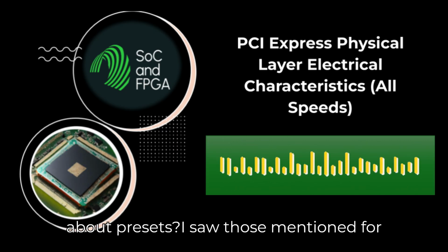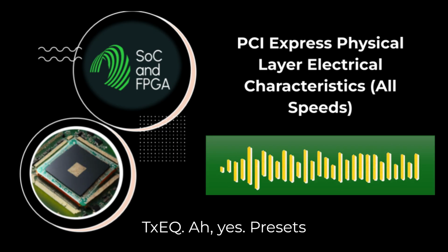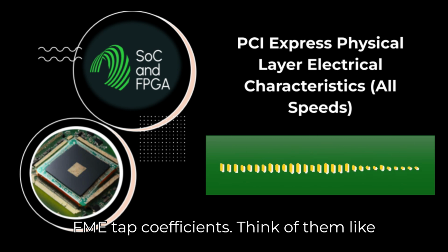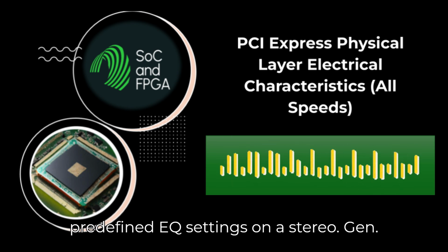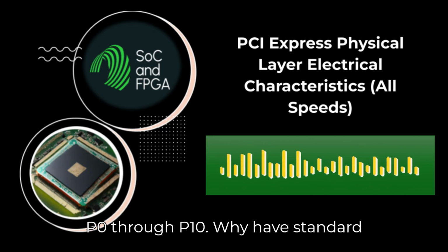Okay. And what about presets? I saw those mentioned for TX-EQ. Ah, yes. Presets are standardized combinations of these FFE tap coefficients. Think of them like predefined EQ settings on a stereo. Gen 3, 4, and 5 defined 11 standard ones, P0 through P10.